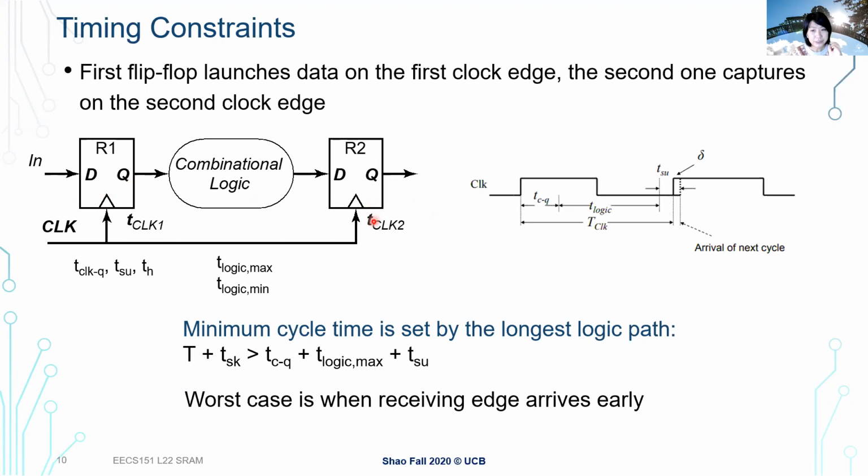Let's say there is clock skew, so in this case the arrival time of the rising edge of my second clock is being delayed. There is a small skew showing up, so my second flip-flop, in this hypothetical example, just has a longer wire. So the arrival time of my clock has a small skew here.